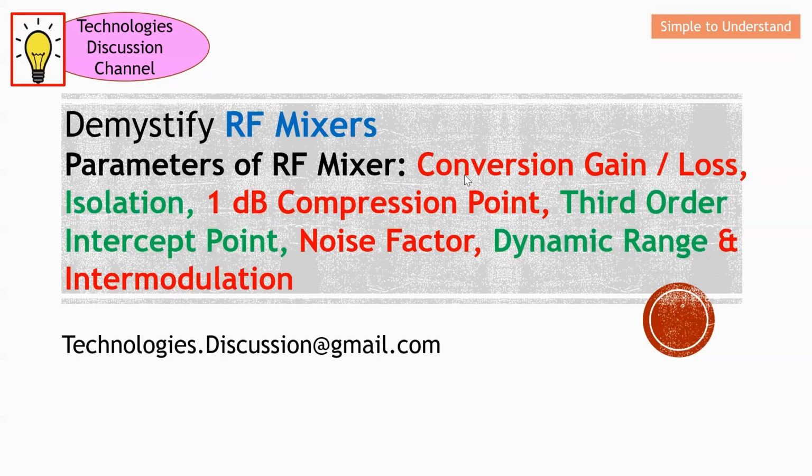For example, we have the conversion gain or the conversion loss. Next will be isolation. You probably need to know what the 1 dB compression point is. Next will be the third order intercept point. Noise factor, dynamic range, which is the range that they are able to operate in on a linear basis. And last but not least, intermodulation. So all this will be the objective of this video.